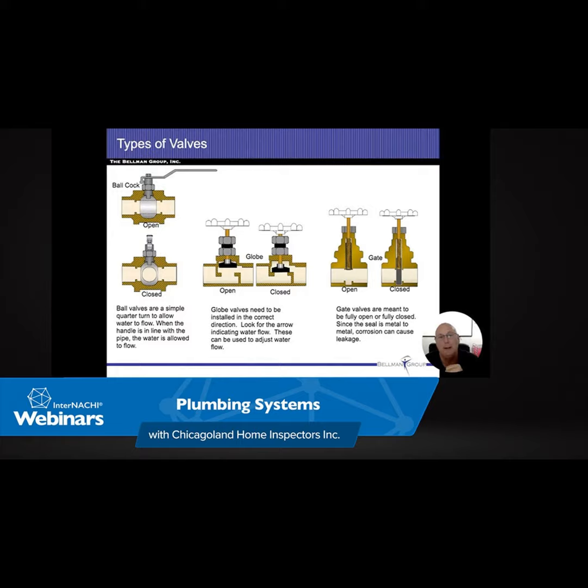So that cold water, it's kind of like electricity. It's going to take that path of least resistance and it's just going to flow straight from the right side over to the left side. And we're going to be running out of hot water in a matter of a few minutes. The tank will be filled with hot water. We're just not going to be able to use it because as the hot water is leaving, it's being replaced with cold water at the top. And the wall of water in the rest of the tank just is sitting there. It's not doing anything. So that's what the dip tube is for. Bring it down to the bottom.